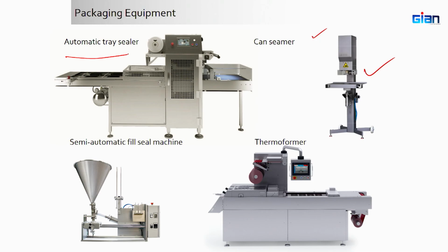The problem comes with these types of tray sealers if the bottom material is made up of PET or polypropylene and the top one is LDPE. So, recyclability becomes challenging. Yeah. If we have a bottom plate of polypropylene as is and the top film is made up of biodegradable packaging film, it solves the problem.